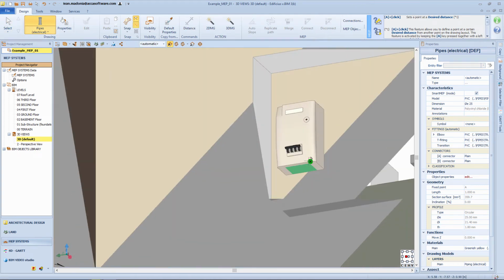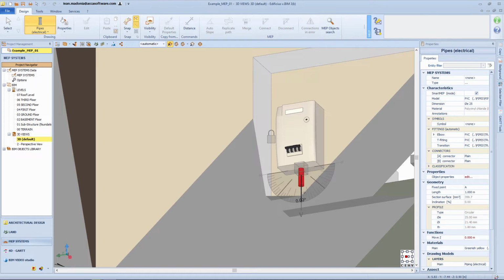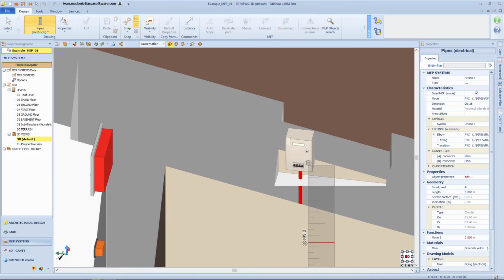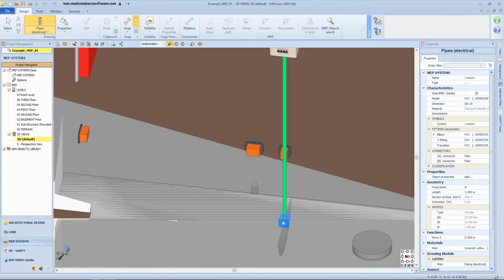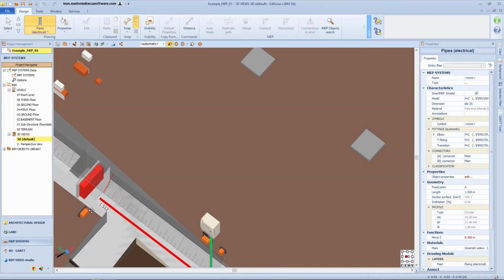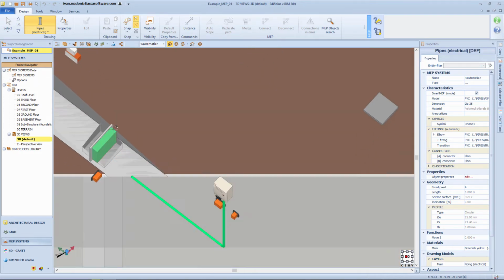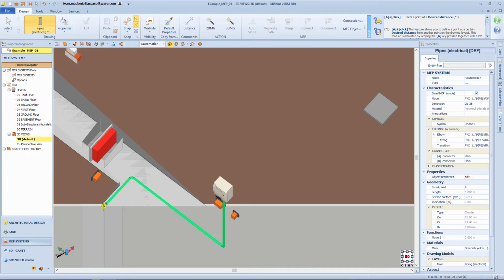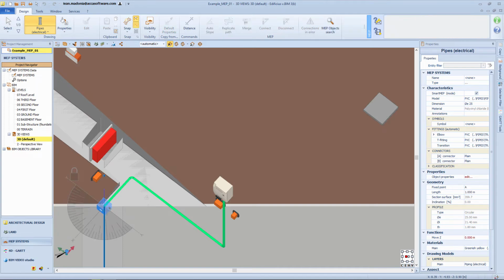Any surfaces that are ready for a connection are colored green. When an area turns yellow, you can click to start tracing a pipeline from that point. This enables the directional cube and the protractor to choose plane and direction along which to trace the connection, followed by the 3D ruler to fix its length. Starting from a first section, you can continue to trace with a second section of electrical piping in a different direction. Provided that the Smart MEP mode is active, the curved type fitting is automatically inserted to connect the two segments correctly.